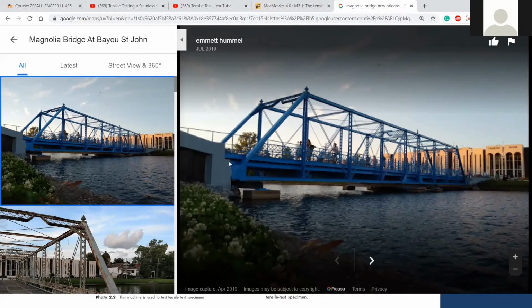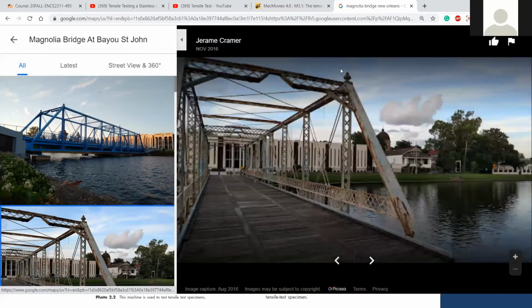So this bridge was corroded. We had to cover the bridge, tarp it, because we don't want to hurt the environment, and we had to sandblast it and then paint it. Obviously, before the sandblasting and painting, we had different members to strengthen this bridge. It's called retrofit. So we changed some of the girders, some of the beams, some of the truss, or lattice truss on the right side, and then we painted.